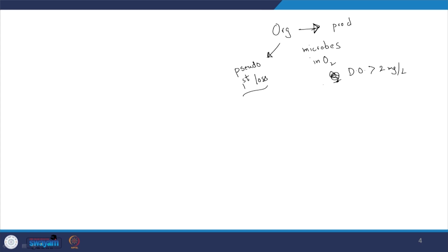Again, this is the case, and let us say K is the rate constant, and to use the usual nomenclature, L is the concentration of the organic content. So, initially I have L naught, okay, L naught, this is not L out. So, in my sample, let us say I want to be able to estimate it, this is my sample, this is a closed system, meaning it is a batch reactor, right. I want to estimate or predict the behavior of this organics, and please note that I am applying the mass balance on this organic content, and this is a batch reactor.